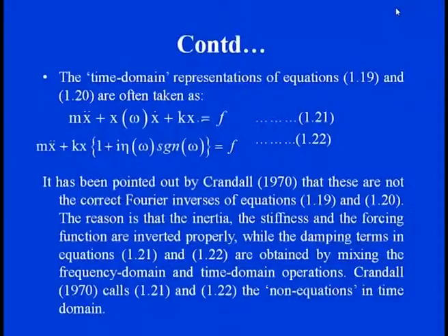And then in these equations Crandall clearly found out that when we are talking about the loss factor, the Fourier inverse equations which we have shown previously are not the correct representation, because the inertia forces, the stiffness and the forcing function are not clearly interpreted and inverted properly when the damping terms come out in a mixing form of frequency domain and time domain operations.